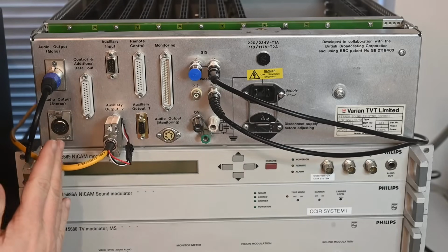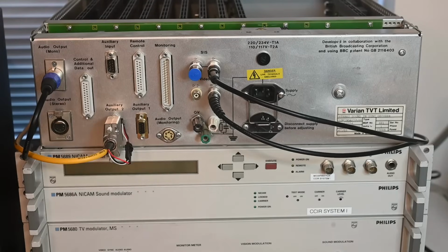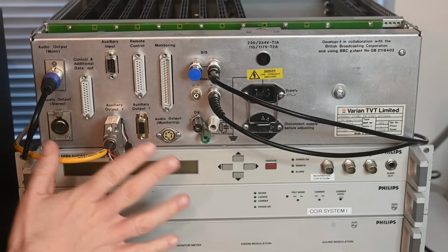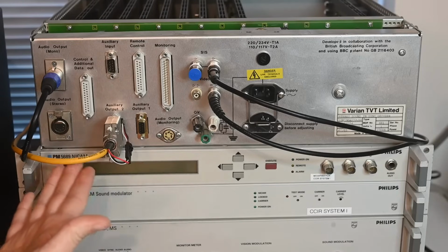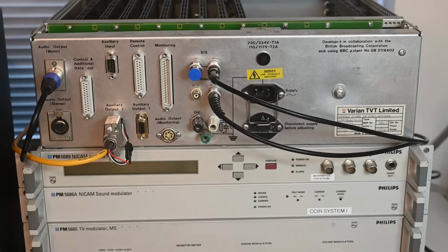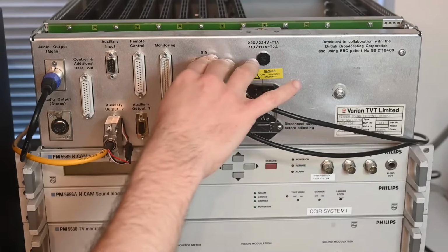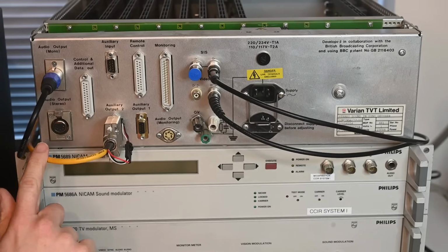This here is that same connection that we saw on the coder, but labeled auxiliary outputs 2 for some reason or other, but it appears to have the exact same pinout as the one we saw on the coder. And this connector is really special for this system. This basically is what allows us to have this end-to-end digital audio, which really is quite unique to the United Kingdom, where the audio is digitized at the source, and it remains as NICAM 728 all the way through to the viewer. So this piece of equipment basically brings the audio in through this cable in digital form, then it exits here in digital without having to go back to analog, and that's just really neat.